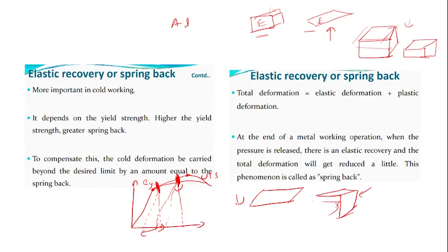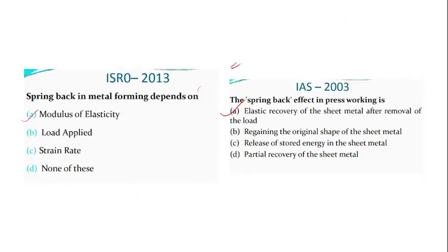Yes. Ma'am, can you go back to that question? Which one? This one? In the 2003 question, yes. Option C also correct: release the stored energy in the sheet metal. See, spring back, what we are considering, is the elastic recovery. So there will be some stored energy after the plastic deformation also, right?